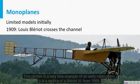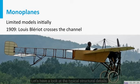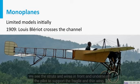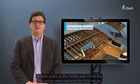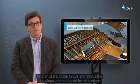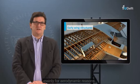This picture is a very nice example of an early monoplane. It is a replica of a Blériot 9 from 1909. Let's have a look at the very typical structural details. We see the struts and the wires in front and underneath the pilot to support the fragile and thin wing. Furthermore, we can clearly see the wire brace truss structure of the tail. In later years, in the 1920s and 1930s, the thin wings were replaced by thick wings, mainly for aerodynamic reasons.